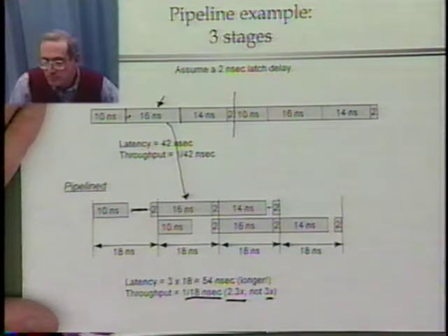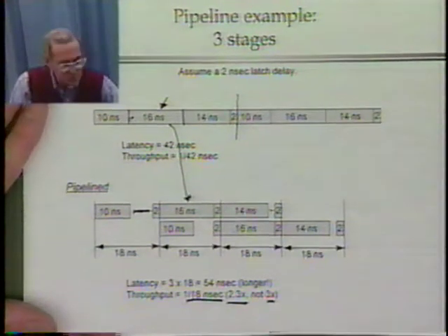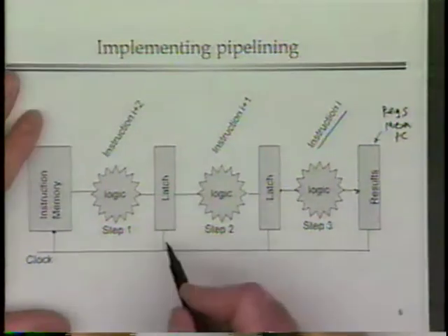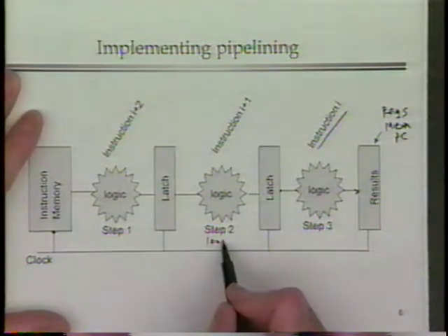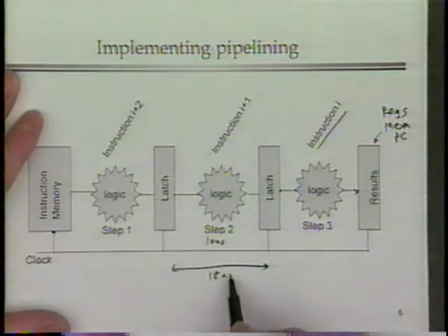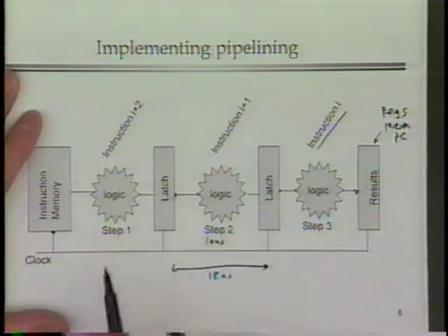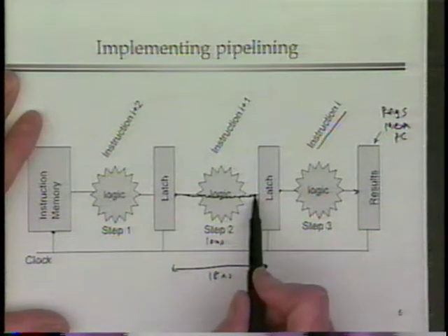They're stored in the pipeline latch. Well, they're sort of stored in the pipeline latch, depending on what you mean. They're actually stored in the combinational logic. If we go back to the simple pipeline, let's say that this stage takes only 10 nanoseconds, and in fact the cycle time is 18 nanoseconds. Well, at the beginning of the cycle, the data is valid at this latch. 10 nanoseconds later, they've made their way through this logic, and they're sitting over here.